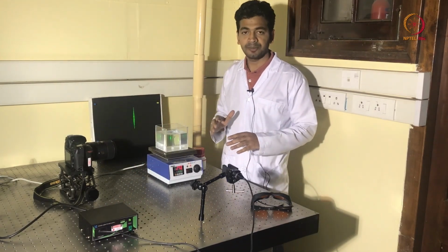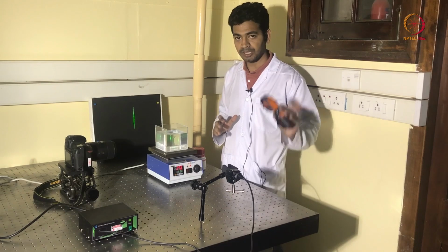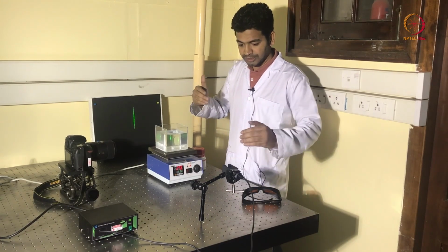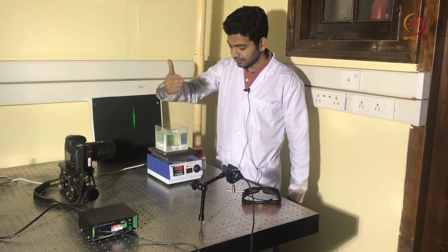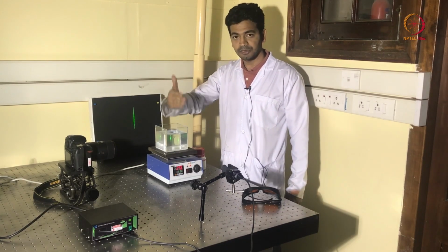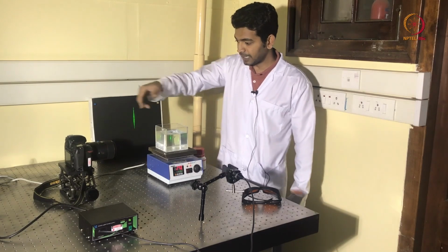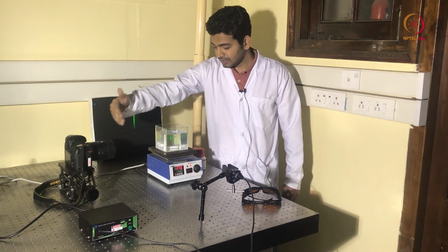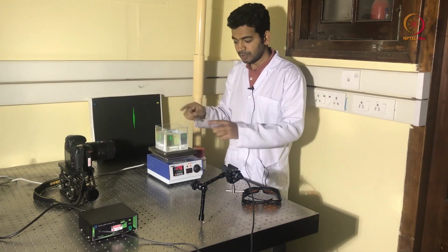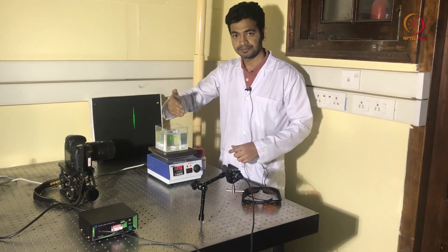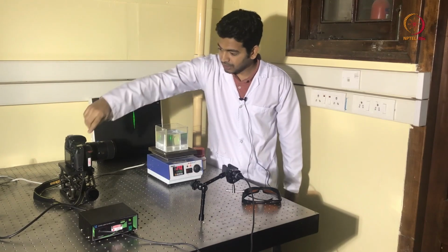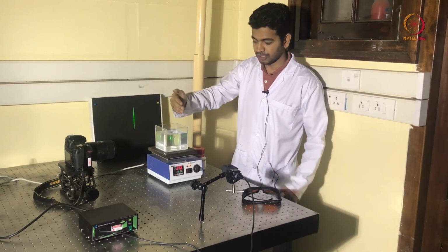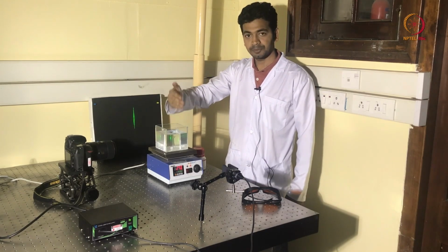While setting up the experiment, you have to be careful and you need to use proper laser goggles. I have already aligned it, so I am not wearing it. Now, as you can see, there is a sheet of light that is illuminating the particles in this particular plane, and then I have kept the camera perpendicular to this plane, and this camera is recording the motion of the particles in that particular plane. So let's take a sample recording, and now the camera is recording the motion of particles in this particular plane where the particles are illuminated.